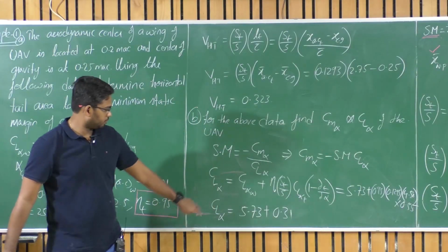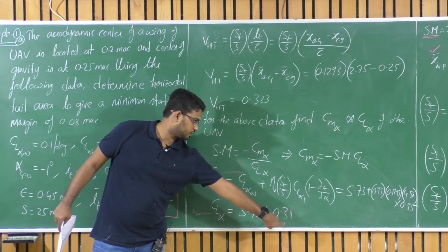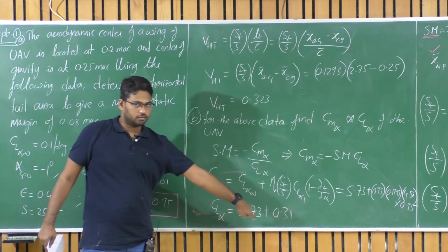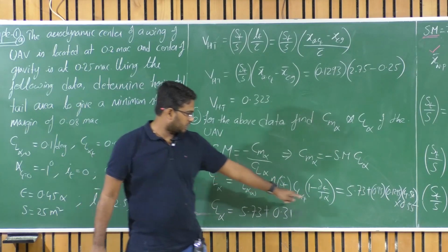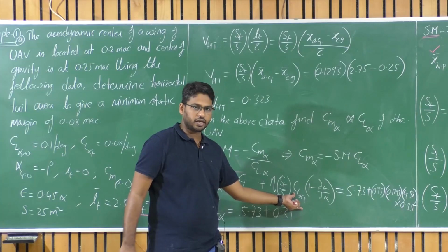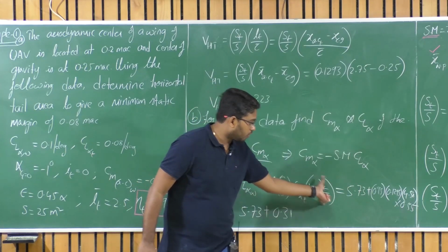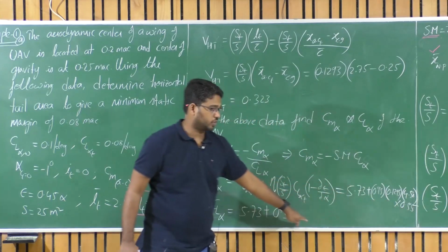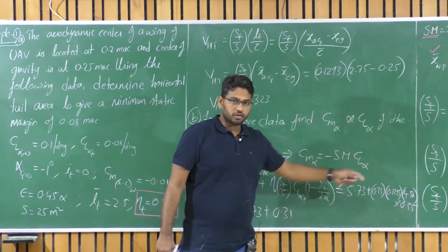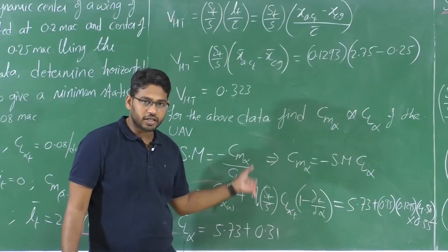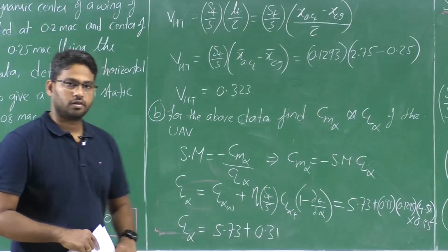So see, the major contribution of the lift curve slope for the entire aircraft is from the wing compared to that of the tail, isn't it? Am I correct? So the major reason is, eta is close to 0.95, that is not going to affect the CL alpha much. It's just almost 95% of CL alpha, and the downwash almost halves that CL alpha, and from that the tail volume ratio is just 13%, so in that half it is making 13% of that half. That's why the contribution is very, very less here, isn't it?